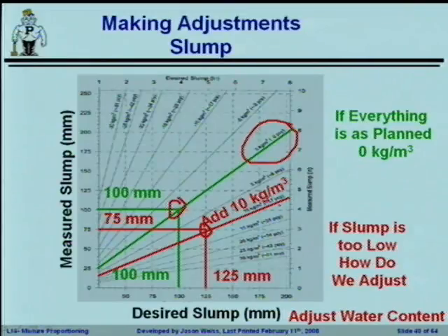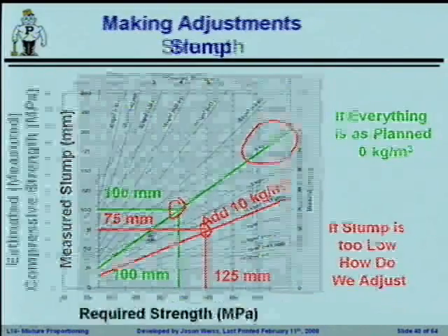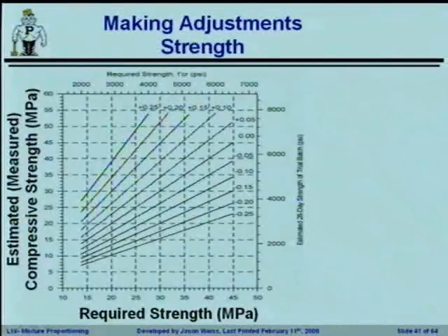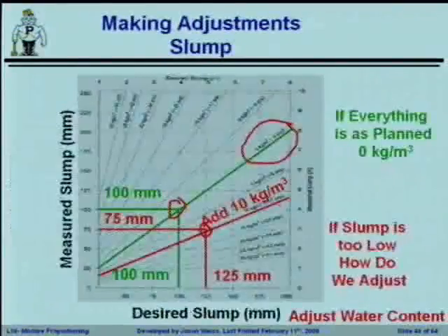You'll remember your water reducers, we gave you some rough ideas. They were 5%, 8%, 12% of the overall water content. You can make an adjustment here to figure out how much that would be for the particular admixture that you're using. Questions on that? Mike? Is it common practice for them to just add water in the field? Like, are these decisions made in the field, or are they made at... No, these would be made in the design process.